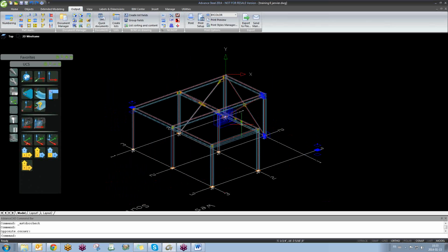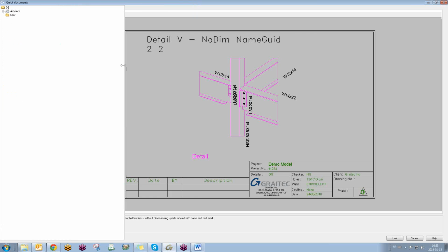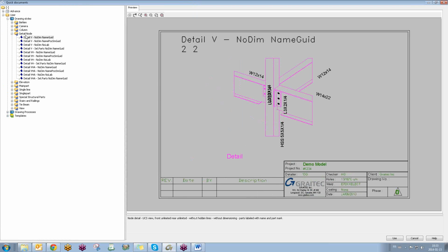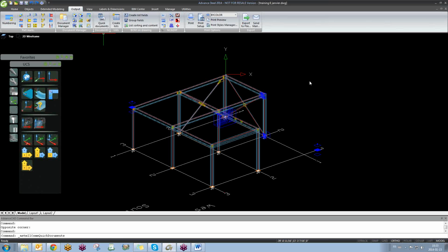Okay. But I thought you just select, so that option you just showed me where you put the window around and selected those objects. Even if the stair is hidden, it'll still pick it up, you're saying? Yep. With both of them here, detail node or the view, it will still pick the stair.